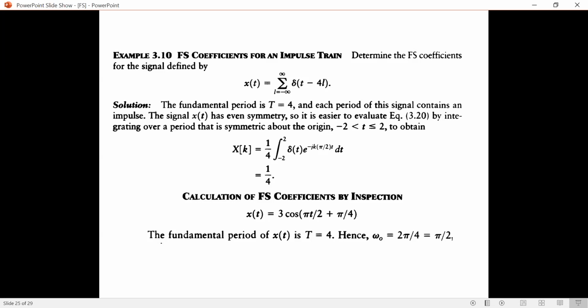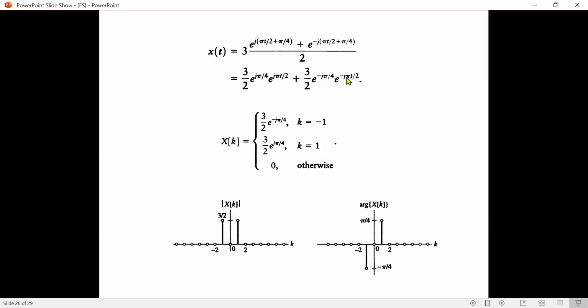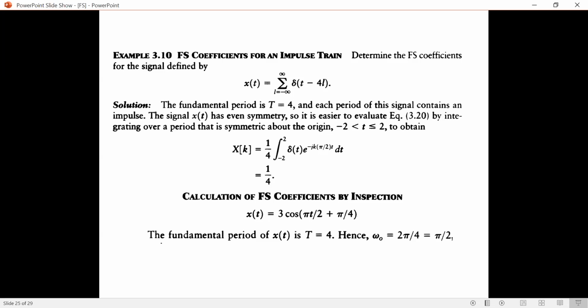Now, another signal, okay? This type of signal we have seen for the case of the discrete time Fourier series, where we used an impulse train, because the impulse train is also a periodic function. And that periodic function can again be represented by complex exponentials, as we have seen there. We have also seen that the Fourier constant xk was independent of the value of k, and it was equal to 1 by N for each value of k. Okay, let us examine